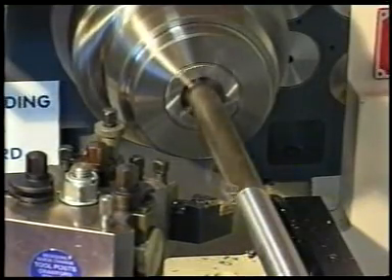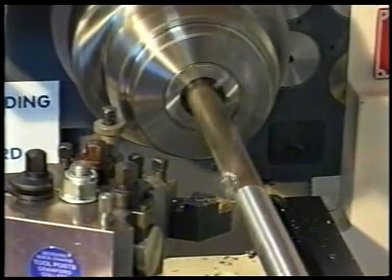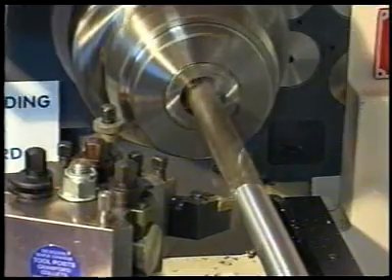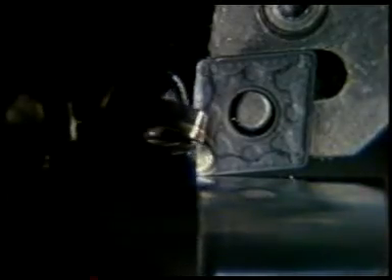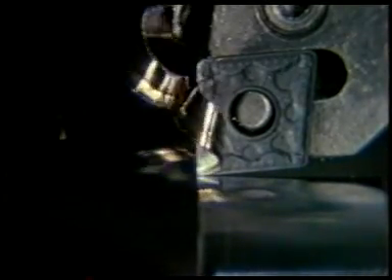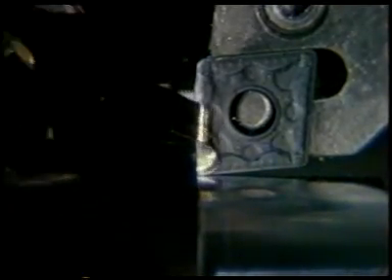The first goal in machining is to achieve the most efficient separation of chips from the metal workpiece. The edges of the cutting tool, driven by the power of the machine tool into the workpiece, force grains of the metal to move away from the advancing cutting edge. This displacement causes the metal to fail. A chip forms along this line of failed metal, which separates from the work material.